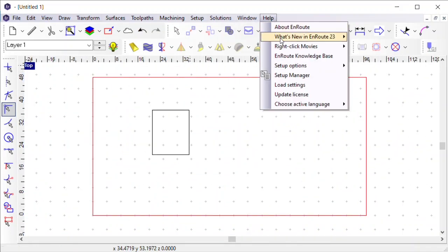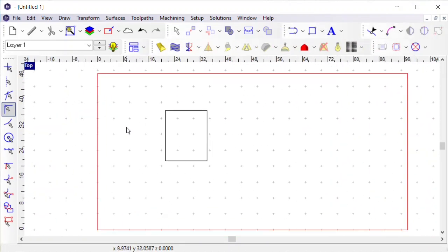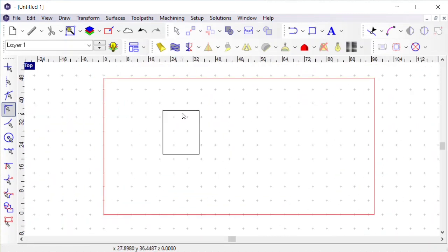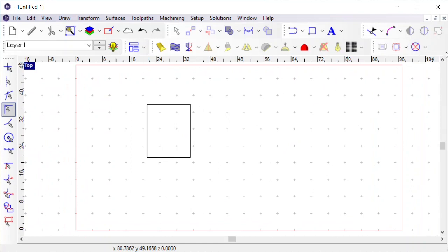And like I said, I just tried the load settings, and that worked great for me, and that brought everything in. There's a few things that will not bring over, like your ATP setup. Okay, I simply did not have the ATP visible because of my adjusted screen size. I have a screen size adjusted for optimal screen capture on video to try to make this the easiest for you viewers to see. Anyway, I had the ATP way over on the right-hand side, could not see it, and I don't believe it's in one of these drop-downs by default, but more on that later. So for now, I just put it right here, automatic toolpath.